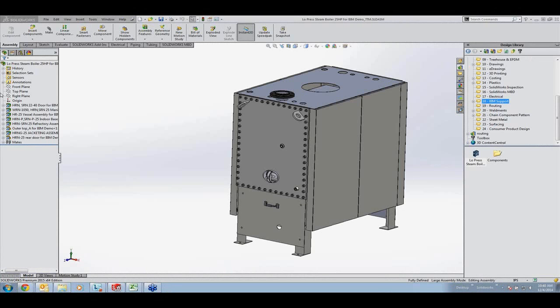I'm also going to create a mate for the beginning linkage. In this case, I'm actually going to use something that you just learned about, the profile center. I'll lock the rotation, hit accept. Once again, it looks like it's broken, but if I rebuild, you'll see that it is not broken. It's not rebuilding.